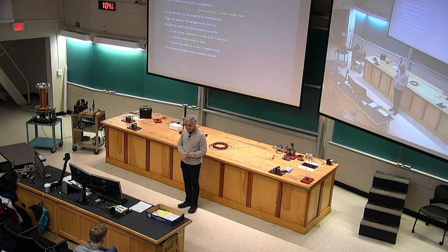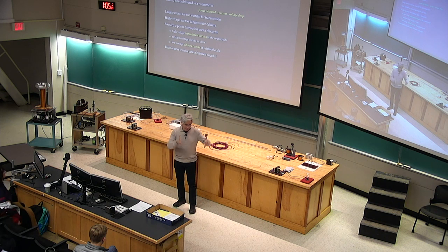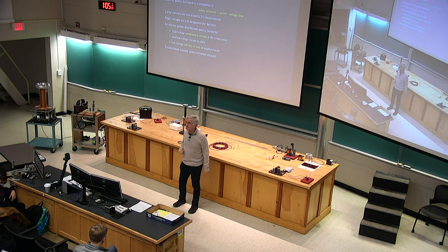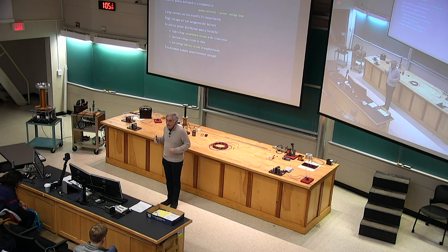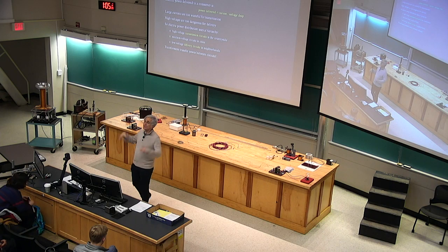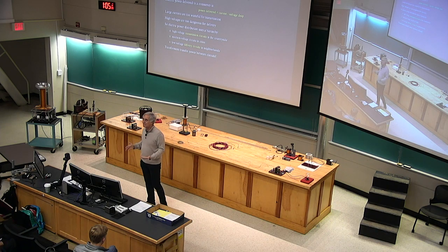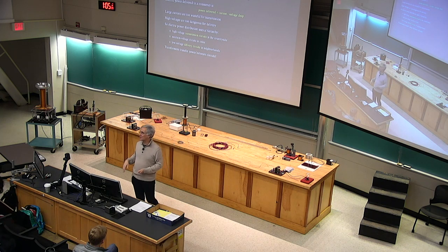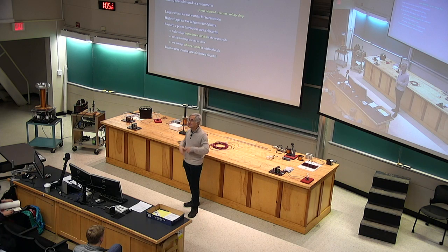So what do you do? Well, that is the problem with the high current, little voltage drop approach. How about the high voltage, little current approach? The power waste in the wires is much smaller. This is great. Because you've reduced the current in the wires, and because wires waste power proportional to the square of the current, dropping the current dramatically is great.